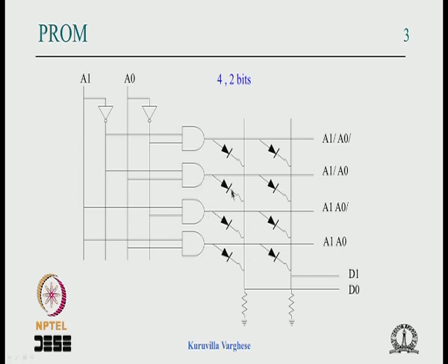So there will be a short circuit directly from the VCC to ground, the VCC of this through the PMOS, or earlier maybe BJTs were used, but it does not matter. From the VCC it is coming through that and it goes to the ground through the transistor pulling low, so there is a short circuit.